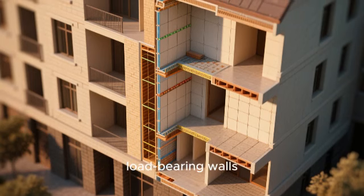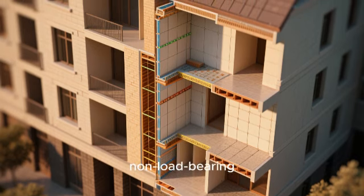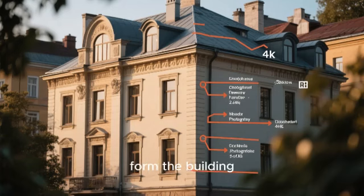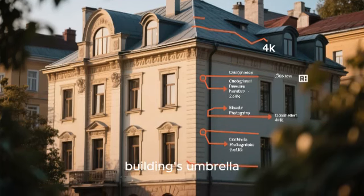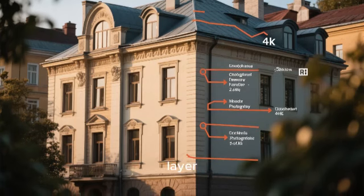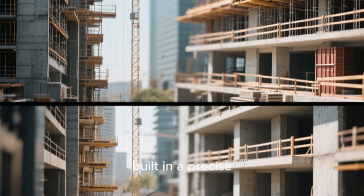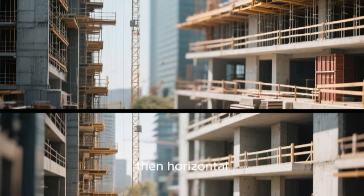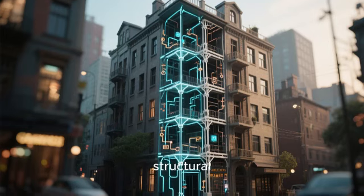We have load-bearing walls that carry loads to the foundation, and non-load-bearing partition walls that just divide space. The exterior walls form the building envelope. Finally, the roof is the uppermost part, the building's umbrella, consisting of a structural system and a waterproofing layer. The efficient workflow secret is that the superstructure is built in a precise sequence, vertical elements first, then horizontal elements, and repeat.